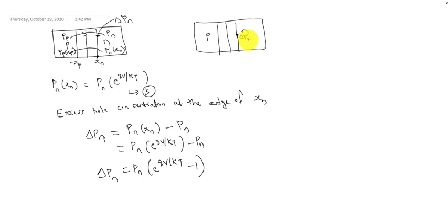So we have already studied the steady state diffusion equation. Before that, this is the case for holes. So similarly we can write the expression for electrons also. So this is equation 4. Similarly, electrons are diffusing from N to P. So Nn is the equilibrium value on n side, the majority value on n side.